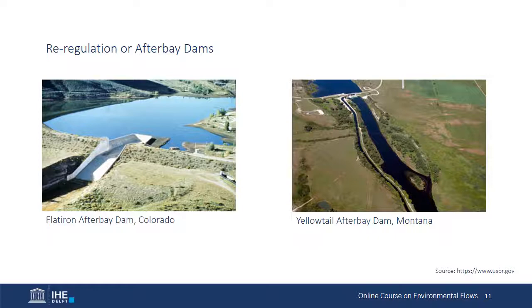In this combined system, flows from the upstream dam can be released to maximize hydropower generation, while flows from the re-regulation dam are released to meet e-flows objectives. Additional power can also be generated from the releases of the re-regulation dam. This approach still results in a reach of altered flow, which impacts connectivity in the river system, but alterations to longer downstream reaches can be minimized.